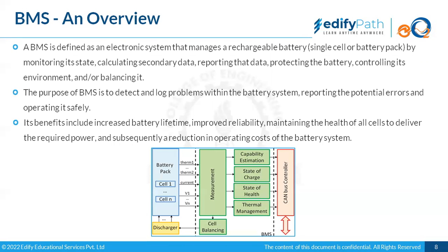That condition occurs when the disbalancing of the battery takes place. Disbalancing in the sense that some cells are either discharging fast or charging fast. In that case, the BMS thinks, from the data that is coming to it, that this module has reached its lower end voltage. It would then consider that the battery has been discharged, so it would disconnect and not allow the battery to discharge further. In that case, the mileage of the vehicle will drop down.